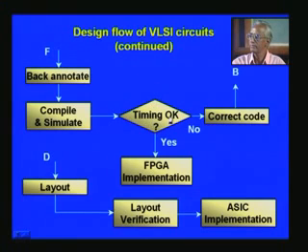So if it is okay, then what you do is you go on to the FPGA implementation. Otherwise, you have to go back to compiling once again and go through the entire design cycle that you have done earlier till you are totally free of all timing problems, right? And as I mentioned before, the whole thing is just iteration till you settle down onto the final target.